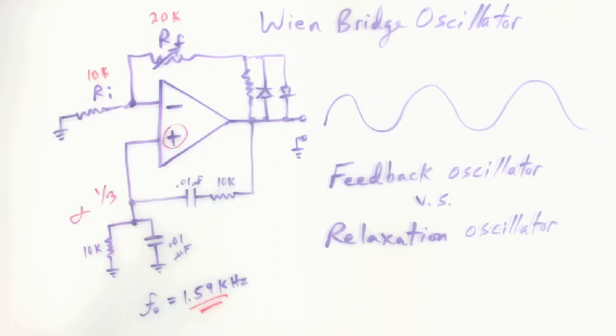So relaxation oscillators are basically a capacitor charging up and then reaching a threshold, where it then starts to discharge down to a lower threshold. When it hits that, the circuitry switches so that the cap will start charging again. So when you have a cap winding up and winding down, charging and discharging between two thresholds, that's important. We said you can't have a single threshold; it'll just oscillate very rapidly, above, below, like very high frequency noise. So you need the two thresholds, and then that would be your hysteresis.